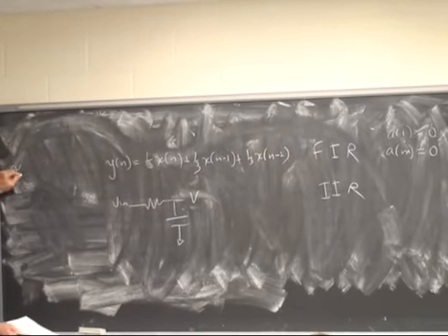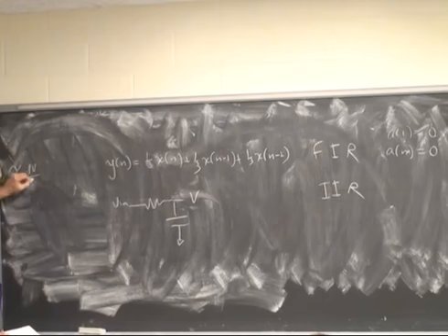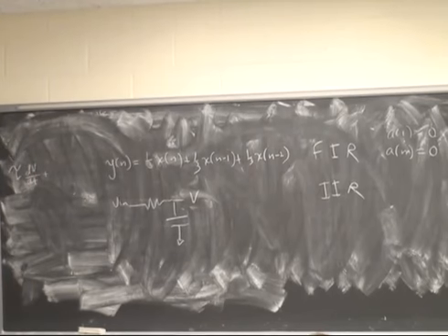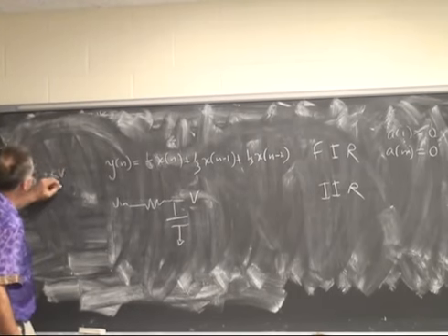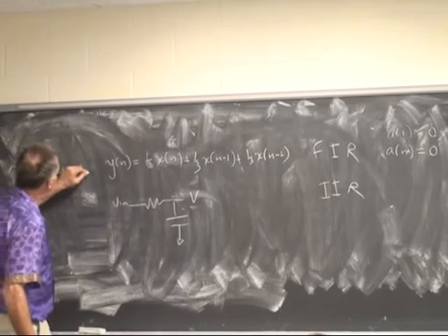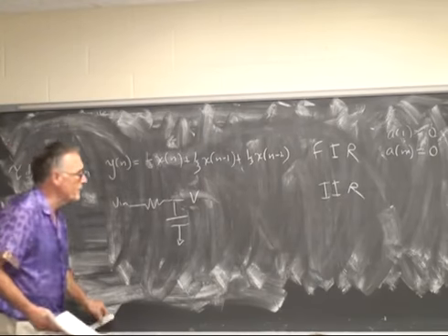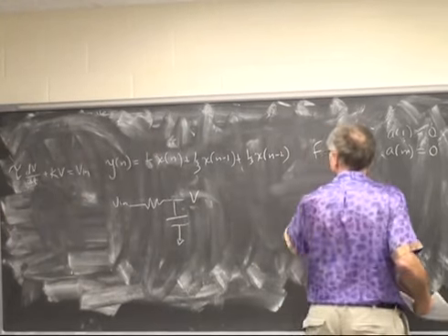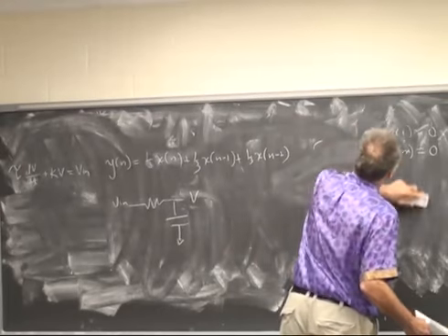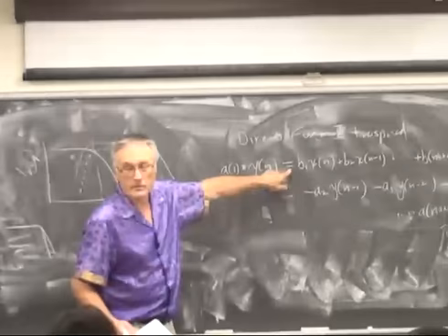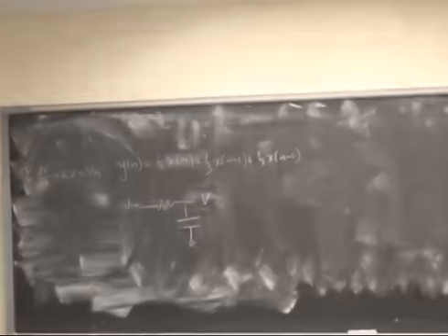So we have that tau dV/dt plus some constant times V is equal to V in, from Kirchhoff's laws. And we can rearrange this, and then we have to use some scheme to convert it from a differential equation to a difference equation to quantify it, to get it into this form. All right, so we want to convert it from a differential equation into this form.